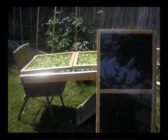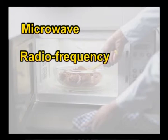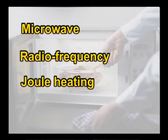Drying. Drying of a food material occurs when water vapor is removed from its surface into the surrounding space, resulting in a relatively dried form of the material. Drying differs from the dewatering process. In dewatering, liquid water is drained or squeezed out of the material, but during drying, the heat can be supplied in different ways: convection, radiation, conduction, microwave, radio frequency, or even Joule heating.